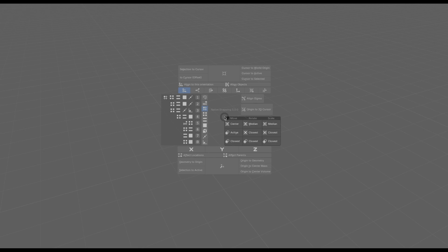They are distributed among the tools: Move, Rotate, and Scale. There are 20 combinations for each. However, 2/3 of these combinations are dispensable because they are repeated or do not work. The function, Origin for the 3D cursor, is also in this menu for convenience, as well as the Align Rotation function, which is useful for aligning gizmos, especially in the orientation mode, Cursor.